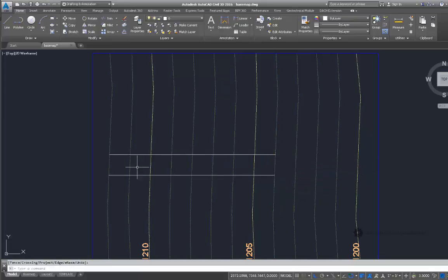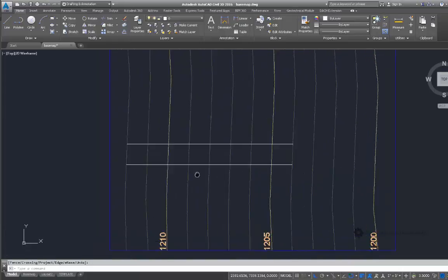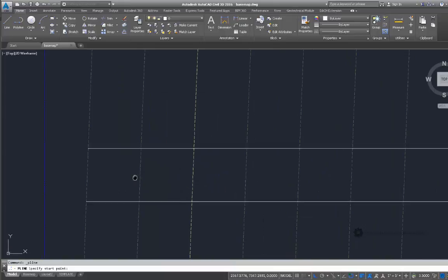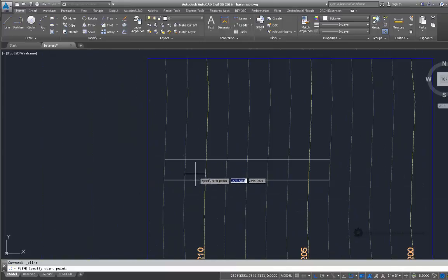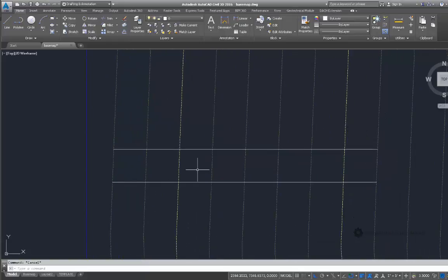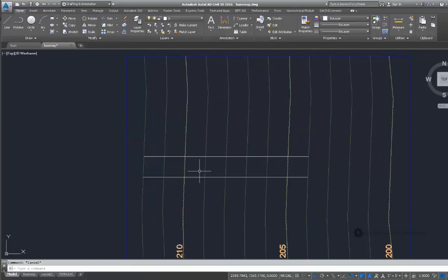And this is our ramp. So we need to figure out how these contours are going to behave along this ramp. So again, I'm going to use the polyline tool, and I want to make sure that I'm snapping to that elevation. So before I do that, I need to figure out, let's just say that this contour is not going to move to where this contour's position is. In this particular example, it's kind of handy that it is, because you know exactly where to move this contour to. But that's not the case. Let's just say that's not the case.